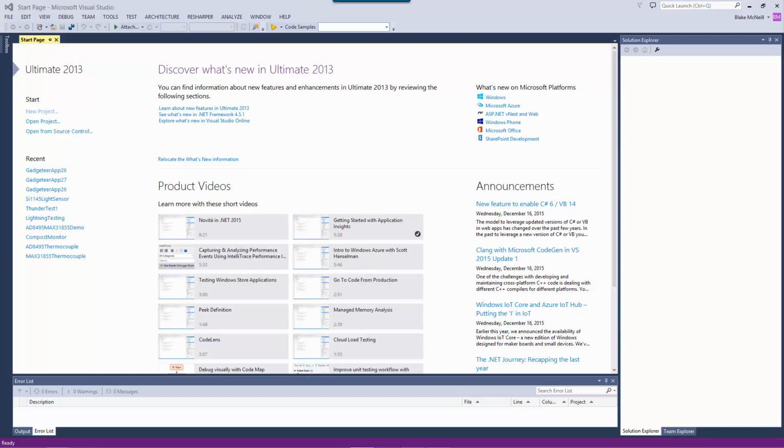Well, ideally, what I'd like to do is measure the chip temperature and see how much it rises above ambient, and then test this against various motor speed settings. As with pulse width modulation, the control power usage shouldn't vary across different speed settings. So the question is how to test or otherwise prove this.